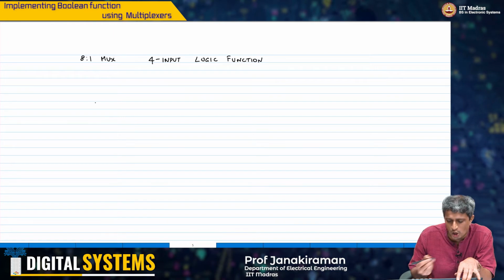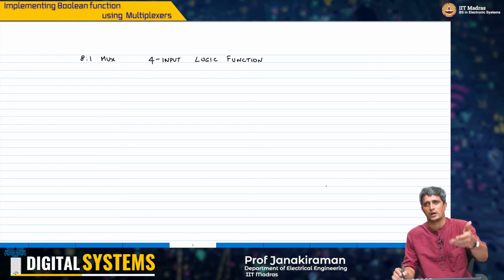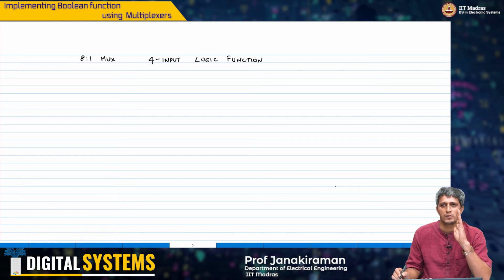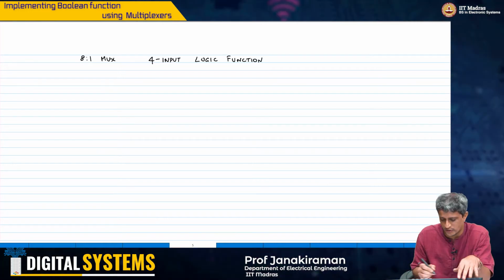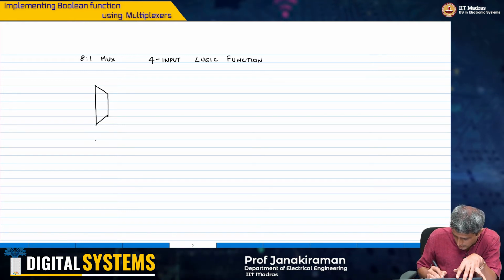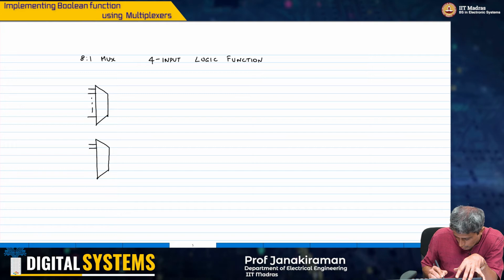So normally the way we would have done this, right? What would we have done? Going by our earlier discussion, we would first implement a 4:1 multiplexer using just 2:1 multiplexers first of all, right? We would have said simply consider 2 multiplexers at the input, right?